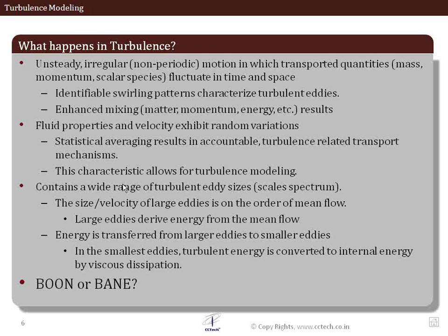So we have higher pressure drop, and that's why we have a trade-off here, that we have to ask ourselves whether turbulence is desired or not, whether it's a boon or a bane. Because if turbulence is desired, then we have to pay the cost of the reduced flow pressure.